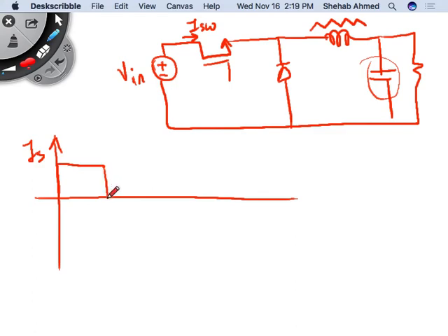When the switch is off, it's 0. Again, do batteries like to be treated that way? No. Batteries are an average power source. They like to provide nice, pure DC current. Otherwise, you're eating from their lifetime, because then you're treating the battery as a transient source, because this is not DC anymore.